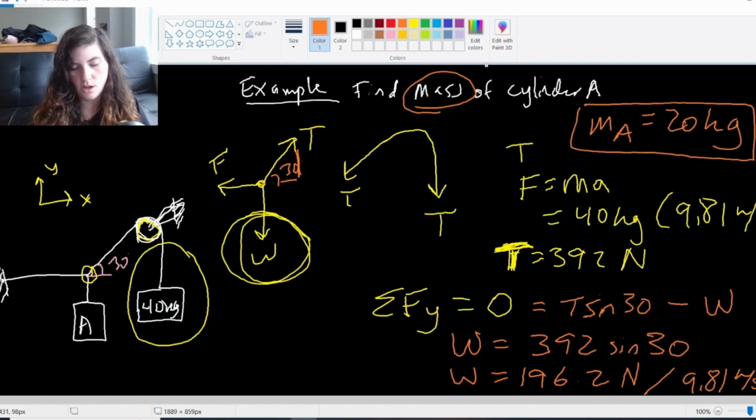and we'll also introduce how you approach this in 3D as well. But for now, just remember the 4 basic steps of how we go about solving these problems in equilibrium, which is setting your coordinate system, making a free body diagram, and then applying those equilibrium equations, which in 2D is going to be the sum of forces in the X direction equals 0, and the sum of forces in the Y direction equals 0. And you repeat that as many times as you need to until you can solve for all of your unknowns.